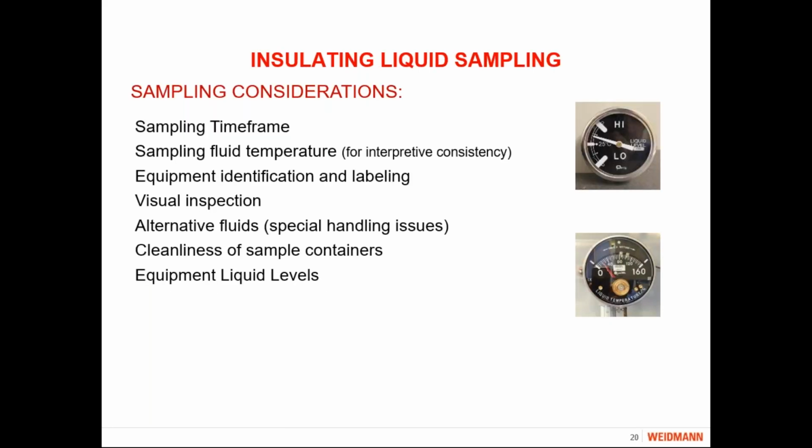Some sampling considerations when you're taking samples, when to take them and such. Sampling time frame just means note the time of day or the time of year that you're taking the sample. Ideally, you would like to take it at the same time of day, at the same day of the year if you're doing routine maintenance samples. And the reason for that is you'd like the fluid temperature to be as close to the same temperature as you can from sample to sample.